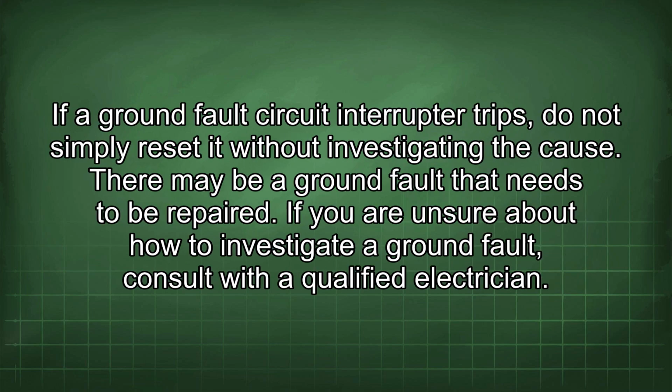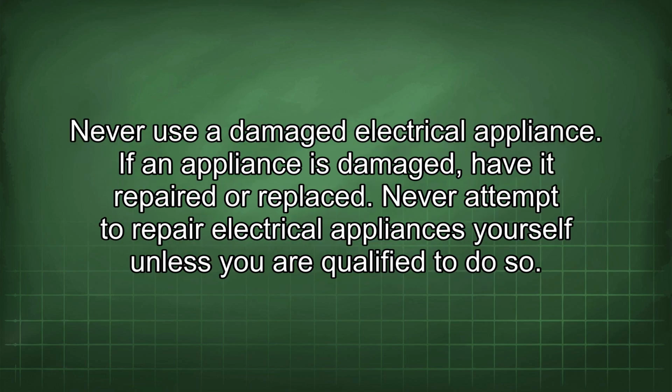If a ground fault circuit interrupter trips, do not simply reset it without investigating the cause. There may be a ground fault that needs to be repaired. If you are unsure about how to investigate a ground fault, consult with a qualified electrician. Never use a damaged electrical appliance. If an appliance is damaged, have it repaired or replaced. Never attempt to repair electrical appliances yourself unless you are qualified to do so.